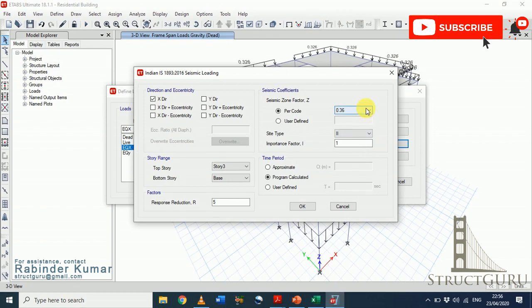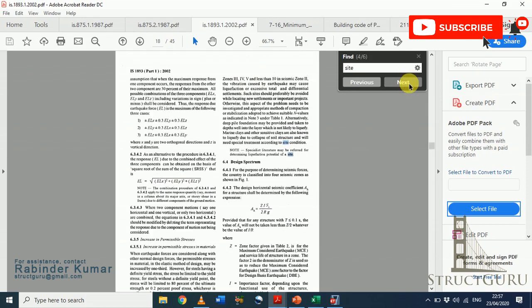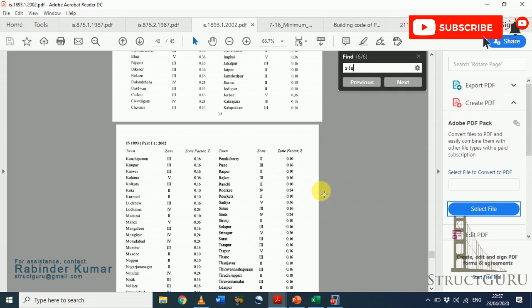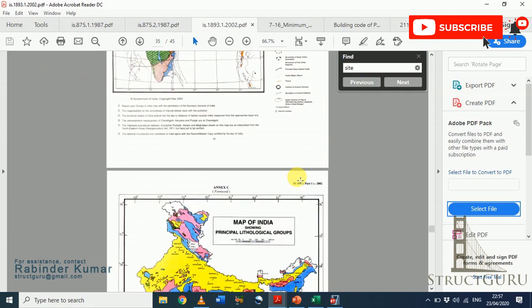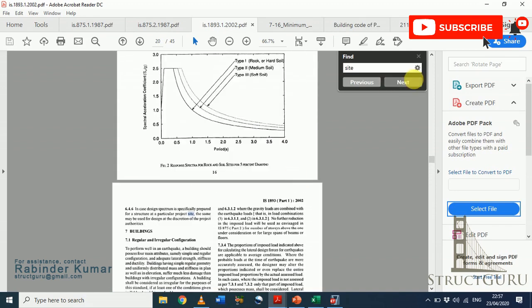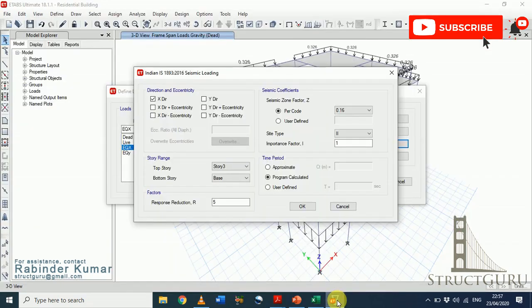So go to the ETABS model, select 0.16. Site type. Again go to the code book. Select site, or choose manually. Site type means whether the soil type is rock or hard soil. This data will be given to you from soil investigation. So for example, I am considering soil type 2.